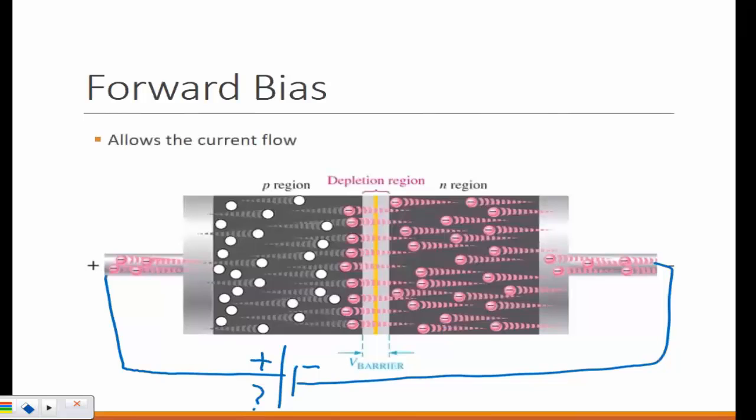But the question is whether it is appreciable current, meaning can I use that current to do something else? Only that happens when this is at least 0.7 volts. If you have more than 0.7 volts, or even at least 0.7 volts, then you have a full flow of current needed. But if you have, let's say, only 0.6, you will have some current, not zero. Are we clear? It's not going to be significant enough to say I have full current in the circuit, right?